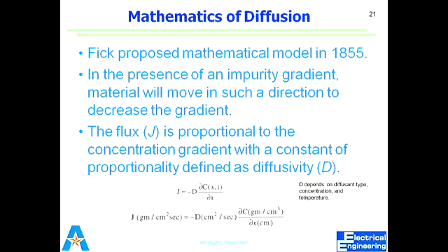It will be of use when it replaces one of the silicon atoms. Since it has 3 electrons, there will be 1 vacancy available, and that vacancy increases my current capability or decreases my resistance. So activating means making my dopant beneficial, replacing the original atom with the dopant. That is what you activate at high temperature. Okay, so that was just one term, because usually